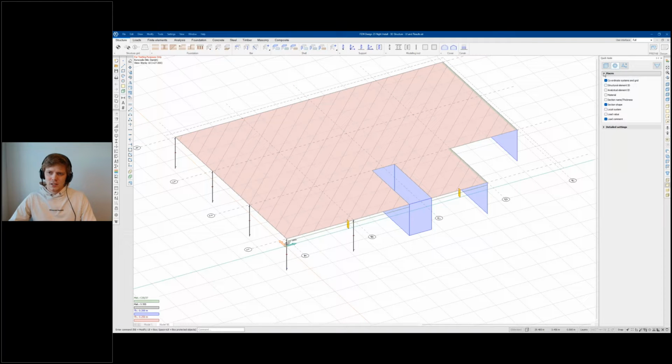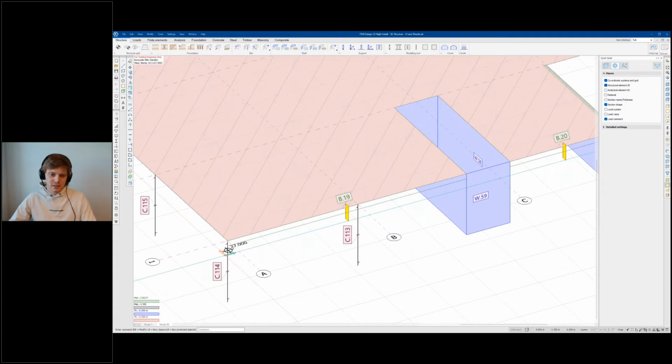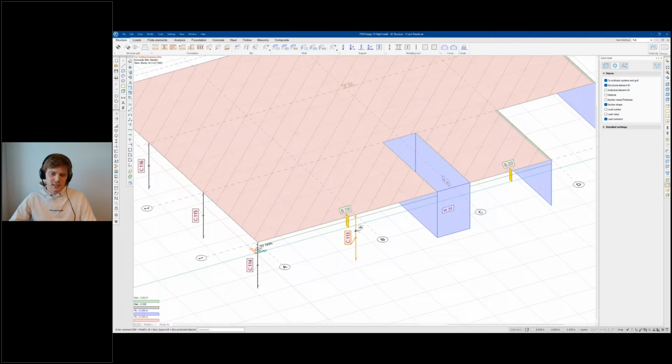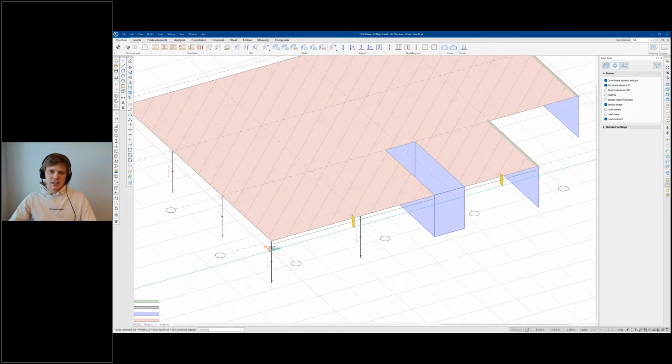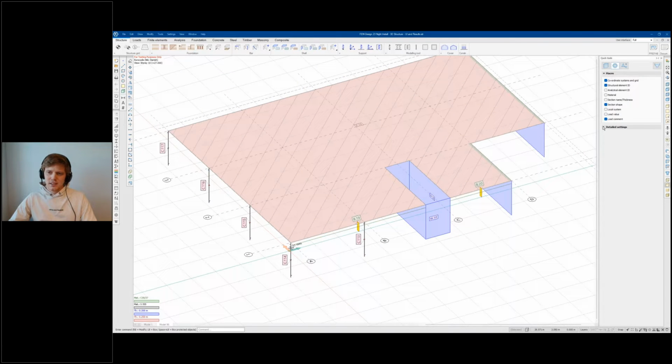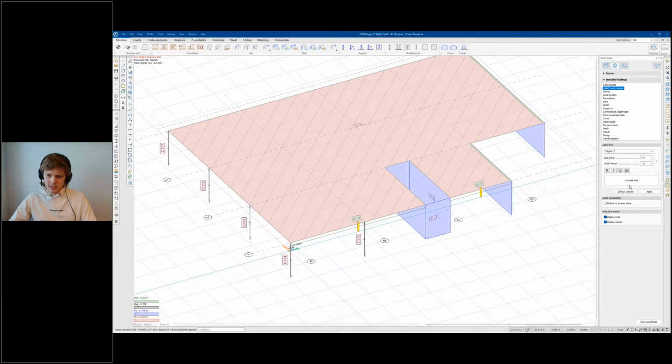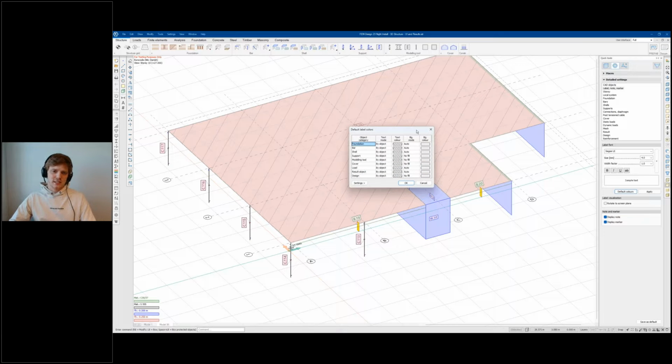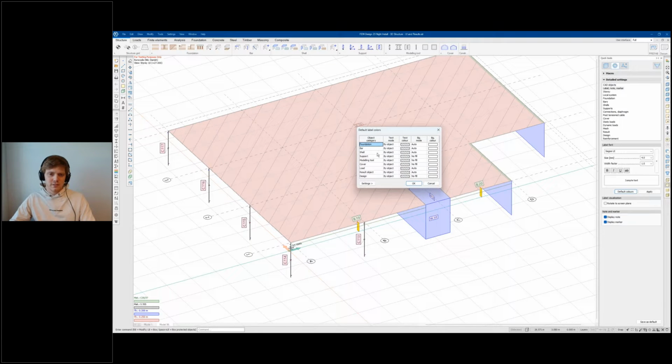If I turn on the ID of my elements, they can now be presented as labels. So instead of it just being a text, it is now a label. This setting is set up inside the detailed settings on the label node marker. Here, on the label font, I can apply colors. It has a lot of default label colors for objects, foundation bars, nodes, and so on.